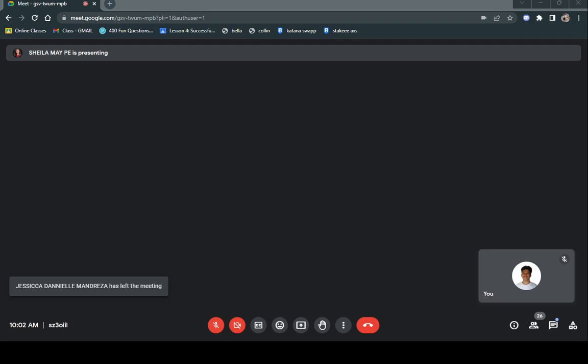Okay, and last is VDS, VDD minus ID times RD plus RS.